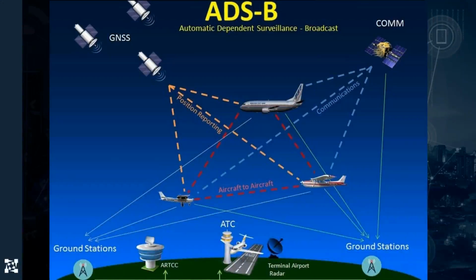And one of the ways that we manage this system is by using ADS-B, right? Each aircraft has a transponder that says, hey, I'm going to use the satellite systems and understand where am I at, what's my velocity, what's my direction, and who am I, right? And we broadcast it, and then other aircraft can listen to that and figure out, is this thing in my way? And if it's in my way, alert the pilot.